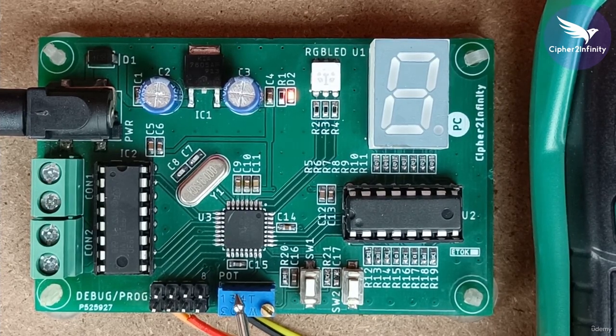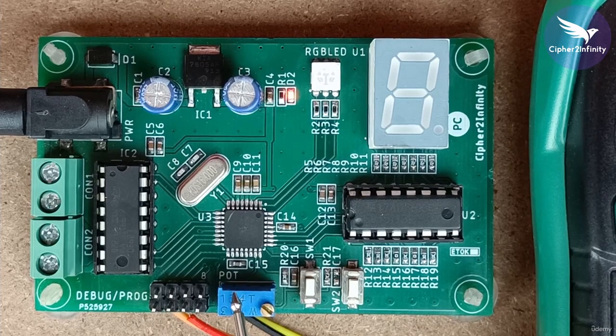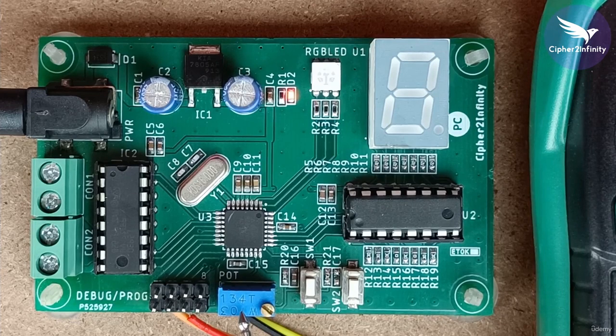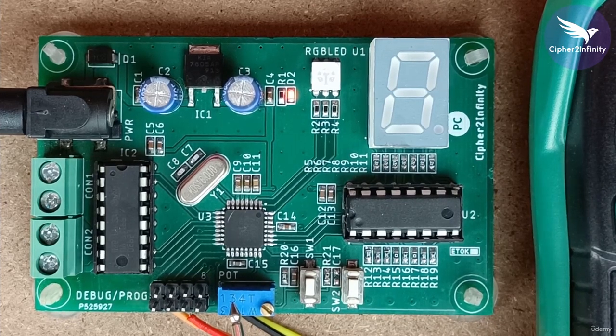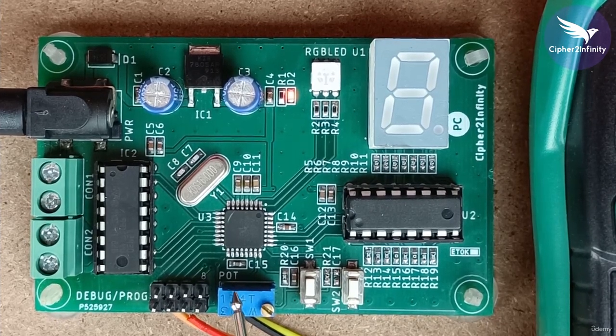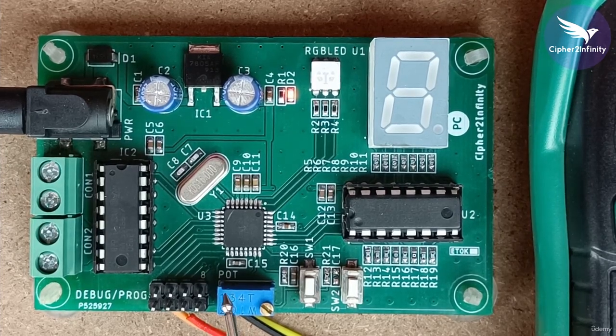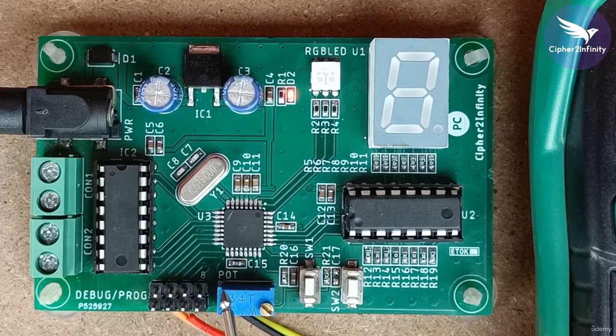Because sometimes it happens that you may receive a damaged preset. You can avoid this kind of situation: instead of directly soldering this preset on the PCB, you can test the preset externally, and once you are sure that the preset is working perfectly fine, you can take the decision and solder the preset on the PCB. So this was the only mistake that you should avoid when you deal with the preset section.